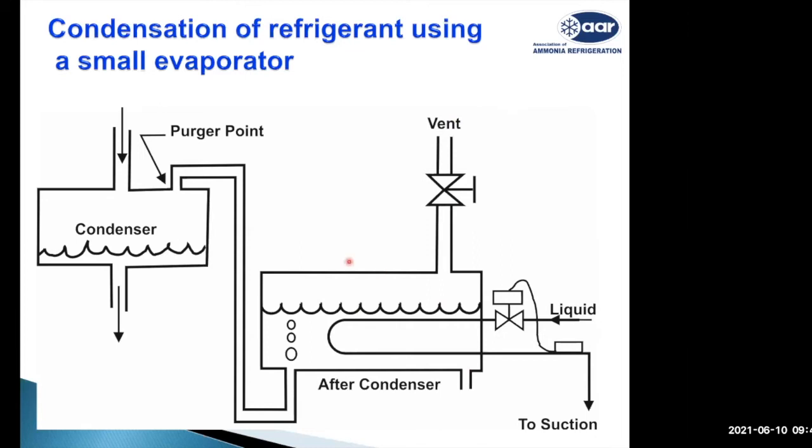Earlier, manual purgers with this same function were also used. They provided multiple manual valves at the purge points and vent points, and you would open those purge valves manually to make sure the air was vented out of the refrigeration system. But now more complex and easier to use purging systems are available.